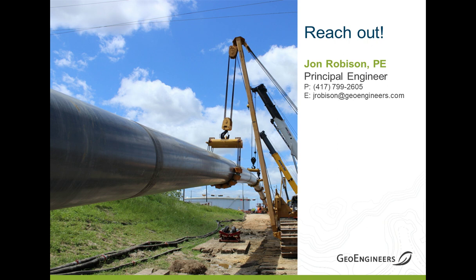I guess it depends on the elevations that you are starting and ending at, and if you only have a 0.5% to play with, then you've really got to be pretty tight on your elevations. If you're trying to drain something at 2% or 3% or something much higher, then you can allow the contractor to have a little more installation flexibility and still meet the slope to drain desire of the project.